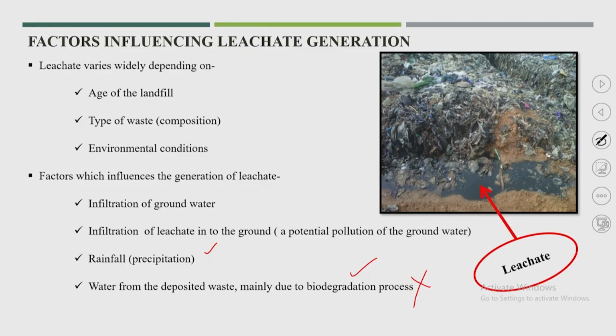And in some areas or localities, especially in the northeast part of India, rainfall goes on for 6 months in a year or somewhere 8 months in a year. So, this could be the most important influencing factor for leachate production. So, you need to look more into daily cover issues in the landfill area.